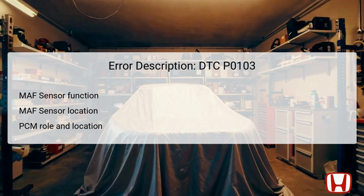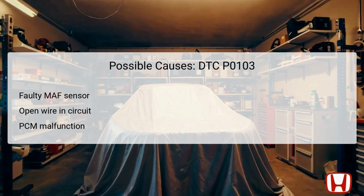Since the PCM relies on accurate MAF data, any malfunction can significantly impact engine performance and efficiency. Thus, a thorough examination of both the MAF sensor and its connections is essential in troubleshooting this error. The potential causes for DTC P0103 include a faulty MAF sensor, which may send erratic readings due to internal damage or wear. An open wire in the circuit can interrupt the signal transmission between the MAF sensor and the PCM, leading to high voltage readings.